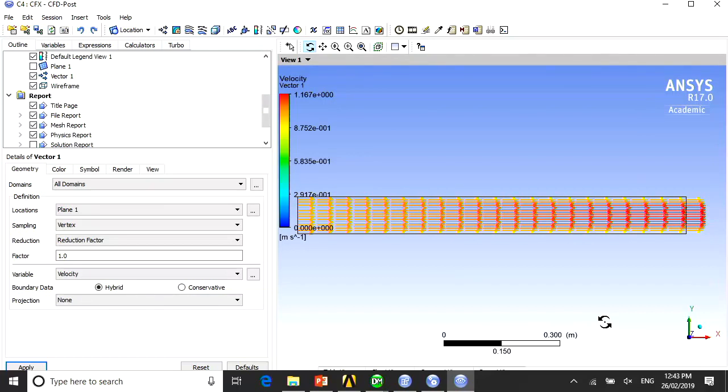True? Correct, right? So that means that if you slow down at the walls, down to roughly, if it's yellow color, roughly 0.8 meters per second, you must have a high velocity in the middle to balance it out, right? So that is how you check your solution to see whether it's correct or wrong.